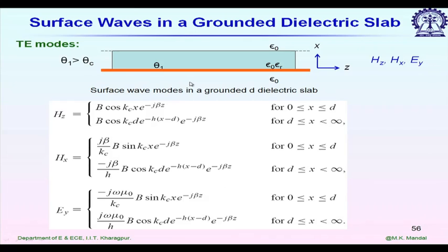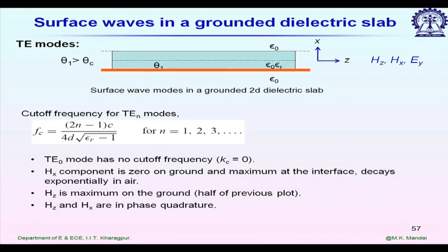So, somehow we have to avoid this TE0 mode or the effect of TM0 mode. In practice, there is no way to completely avoid the effect of TE0 or TM0 mode, but still we have some solution by which we can reduce the coupling to some extent.